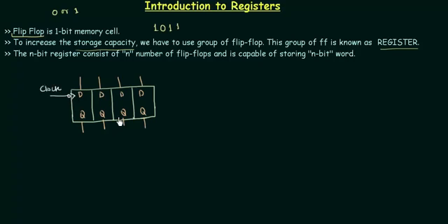Now there is one very important thing that you have to note. The clock is internally connected and applied at the same time. This clock is connected to all these 4 flip-flops internally and applied at the same time. In sequential circuit, clock pulse is not generated individually for every operation, but it is generated and given to all the operations. By this I mean, I'm not going to generate the clock for this flip-flop, then this flip-flop, then this, and then this. I'm not going to generate 4 different clocks for this flip-flops, but I will have a same clock and it is given to the different operation.